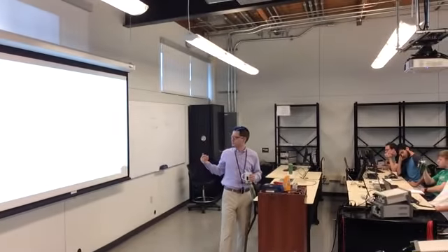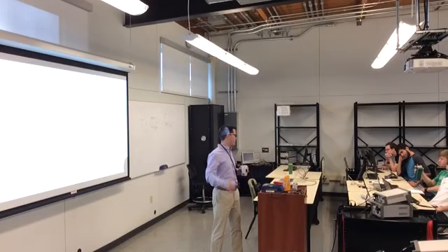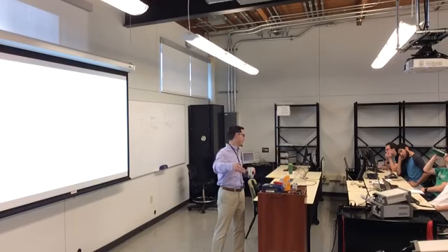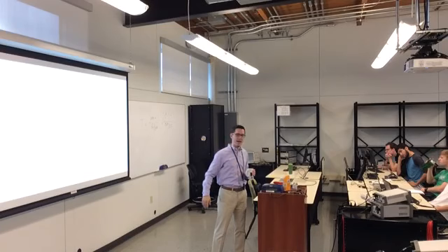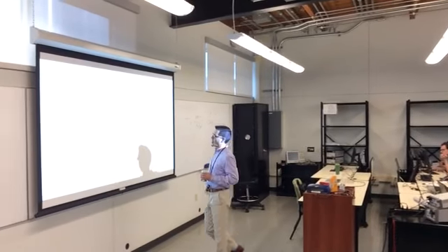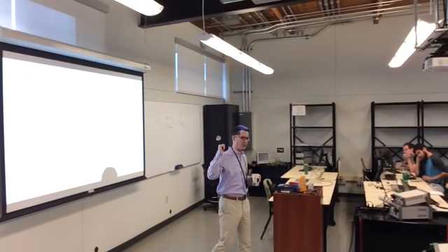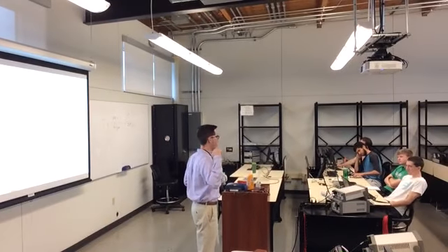What mode is it in? Is it going up? Is it going down? Is it going up, down? Is it in quadrature? Is it in wave counting? Whatever mode it's in. And then for our particular application, you want it to be in debug run mode because you're going to be debugging your processor, and you want the timers to run while you are in the debug mode.